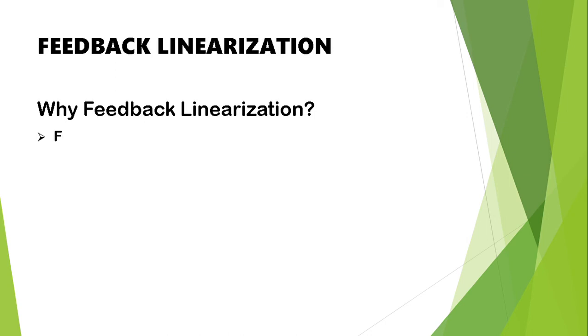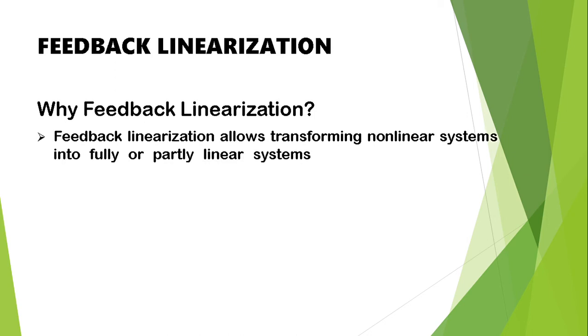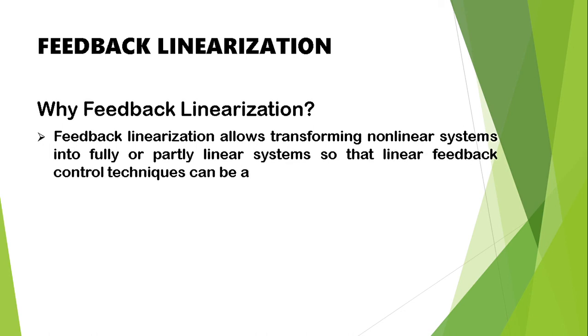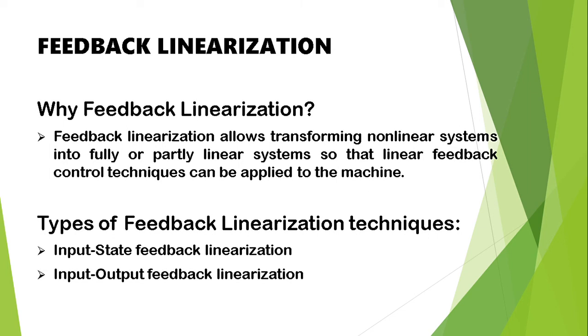Feedback linearization allows transforming non-linear systems into fully or partly linear systems so that linear control techniques can be applied. Now, there are two types of feedback linearization techniques: the input-state feedback linearization and the input-output feedback linearization. For the purpose of this project, we will be reviewing and implementing the input-output feedback linearization.